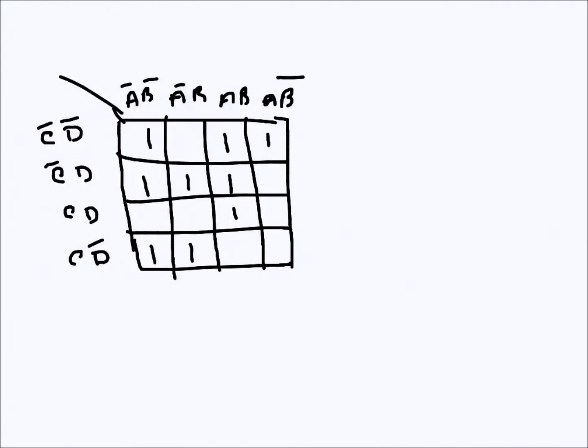Okay, here is an arbitrary K-map. It's actually exactly like the one from the previous video. So the values from the truth table have been put in this Karnaugh map. So Karnaugh map, or K-map, is used to minimize the sum of product expression.